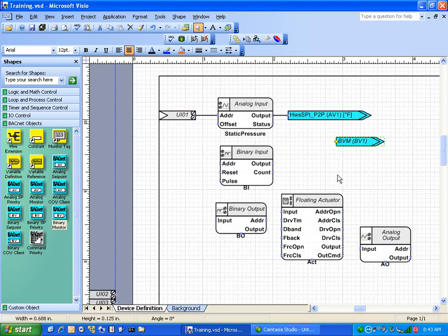In the G3 world, it's really nice because no matter how you set this up, when you learn these objects up in G3, those engineering units and the object name get imported into the object. If you create a log for it, the engineering units transfer right over to the log. If you throw it on the graphic screen for display purposes, the engineering units are right there. So in the R2 world, we're used to having to set that up. If you want engineering units in your log, you usually manually set that up as you create it, which is silly, but that's the way it was.